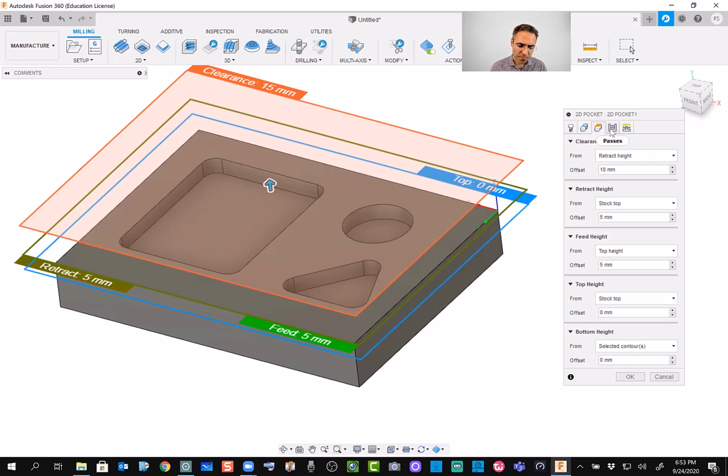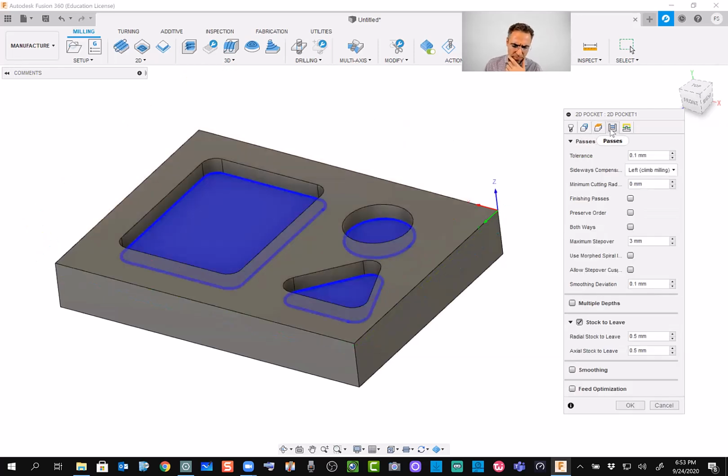The second one, if I click on it, by default the program wants to do this milling for us in one shot. Like the mill goes down and does it in one shot, but it's not a good idea. We don't get a nice, clean pocket. Rather, we should do multiple depths. See here, this word in the middle, multiple depth in this table.